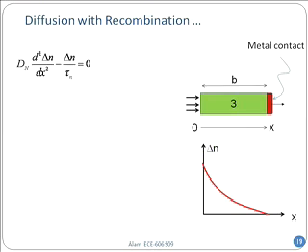Do you know the solution of this equation? That's how it looks. Almost like a Schrodinger equation, right? Does it look almost like a solution of the Schrodinger equation? No surprise, because look, the first term with the second derivative and the potential term on the next one, they are exactly the same equation. Of course, they should have exactly the same solution. So I have that. L sub n is called a recombination length. This is the square root of D n tau n. So that's what it is.